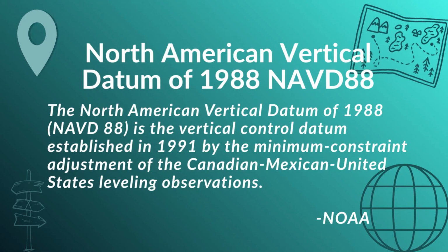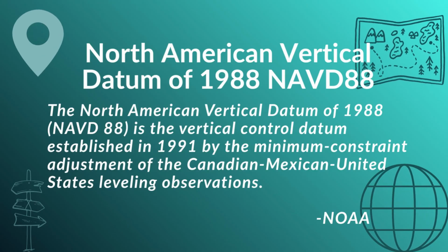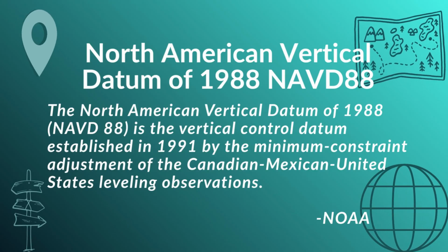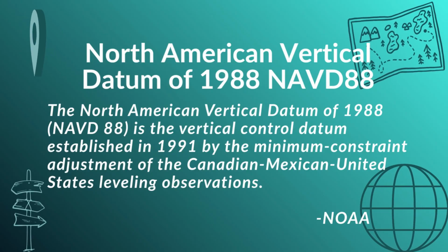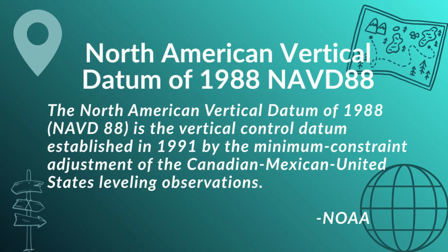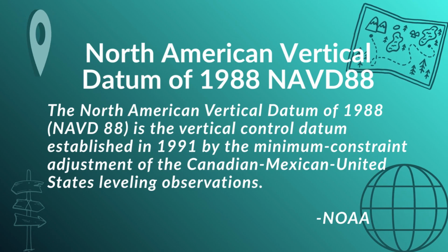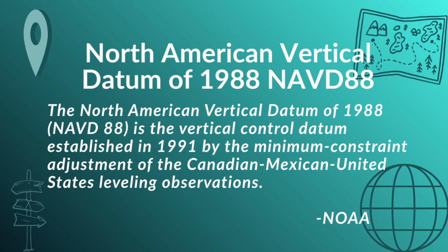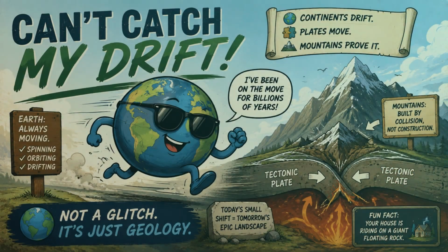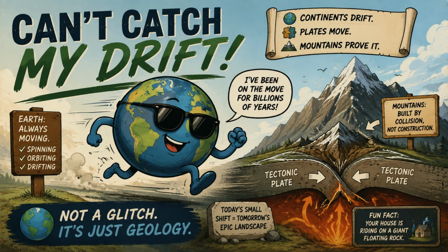Okay, so the study guides place a massive emphasis on datum transformations. As they should. If you take a data set mapped in NAD27 and overlay it onto a map using NAD83 without mathematically transforming it, the coordinates don't physically move on the screen, but their real-world location shifts dramatically. Because the underlying mathematical anchor has moved. A point can shift by tens to hundreds of feet.